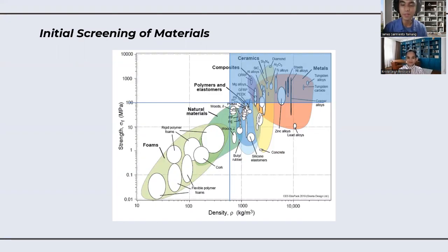So from the figure, the possible material to be used is further narrowed down to CFRP, carbon steels, low alloy steels, titanium steels, nickel alloy, stainless steels, tungsten alloys, silicon nitride, aluminum oxide, silicon carbide, glass fiber reinforced polymer, and polyether ether ketone. Since silicon nitride, aluminum oxide, and silicon carbide are not suitable materials for the reactors because these are ceramics, and glass fiber reinforced polymer and PEEK are polymers, these materials are excluded from the selection.